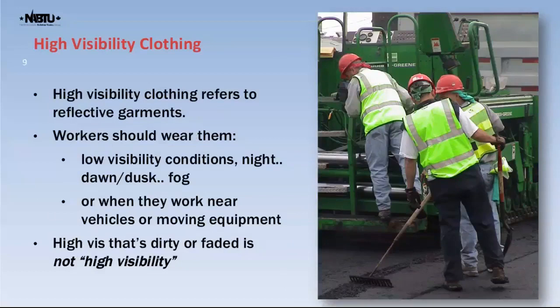I'm sure, when you've been driving around in the evening, you see people out for walks on the sidewalks wearing black and no reflective gear, and you know how hard it is to see people. So when you're on a construction site, you want to make sure you're wearing that high visibility vest so they can see you. And a really important thing here is that high visibility vests oftentimes get dirty because you're working, right? They get dirty and they get faded. And if they're dirty and faded, they're no longer high visibility.